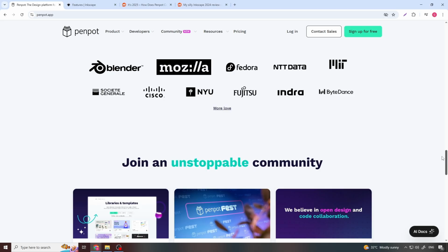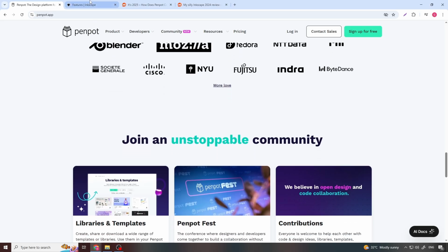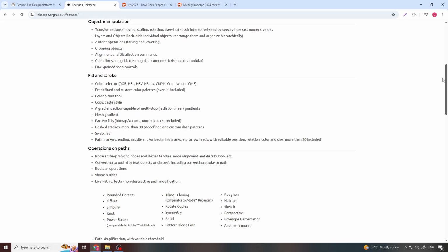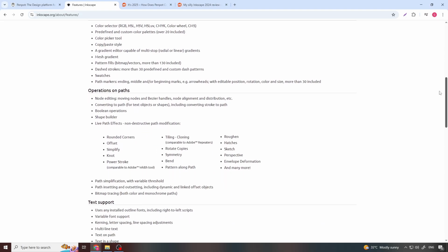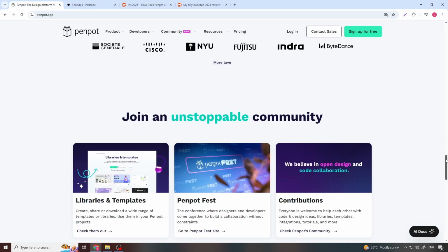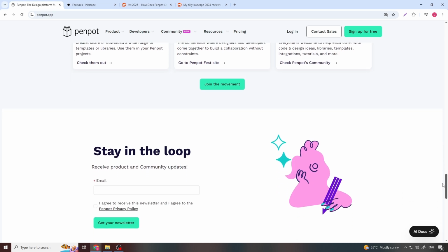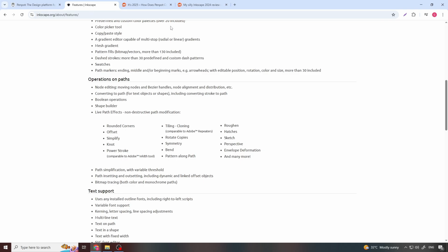The performance limitations are different in cause and character. Inkscape's ceiling comes from a processor-based rendering backend that cannot leverage graphics hardware. The mitigation is to keep documents at moderate complexity or accept slower canvas interaction on heavy files. Penpot's ceiling comes from browser rendering model bloat on large projects with many components. The mitigation is to structure projects to avoid excessive frame counts or accept slower interaction on complex workspaces.